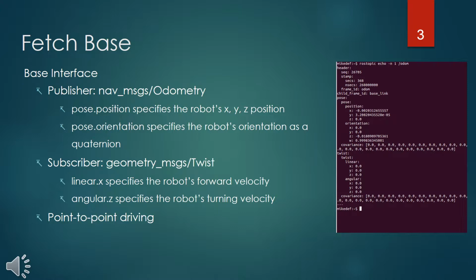Since there is a small error associated with the rotation, when driving forward, the robot will apply a rotational correction based on the angular error to the target. A final heading can also be specified to leave the robot in a desired orientation once it has arrived at its target location. This point-to-point driving can then form the basis for future more complex navigation algorithms.